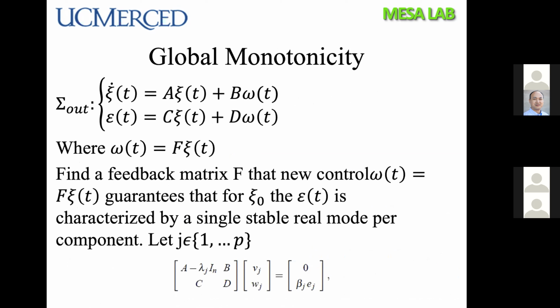To achieve this goal, all the remaining closed-loop modes have to be made invisible from the checking error. If that is possible, then the step reference is guaranteed to be monomial for any initial condition, and therefore also non-overshooting and non-undershooting. Our aim is to find the conditions under which the gain matrix F can be obtained to give the single-mode structure, that is, the structure given in function 8, for any initial condition.